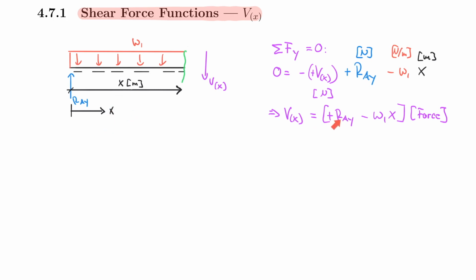And so we now developed the shear force function for an evenly distributed load case. Of course, this is at the left side of the beam, so that is within the first domain, if you will, but this is my answer. So please understand that if something changes here, if I have a different load case on the right, I would have a different domain to deal with. So please understand that we have to think of this as a function per domain, right?